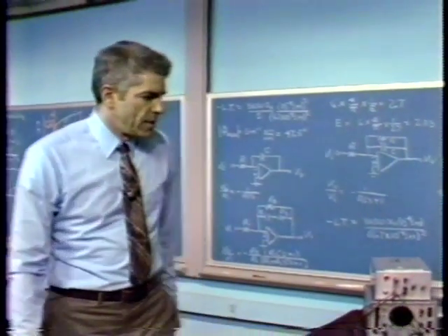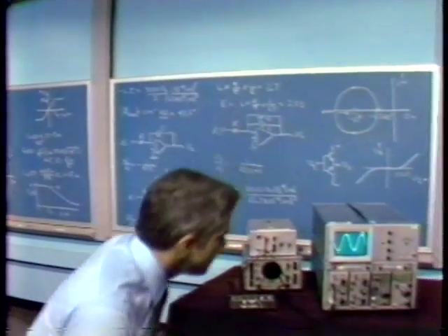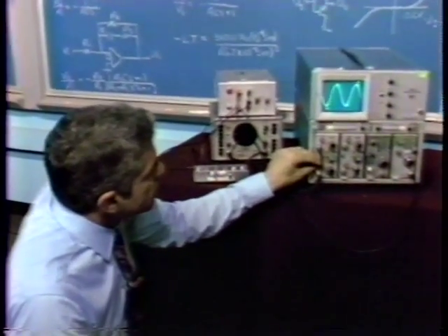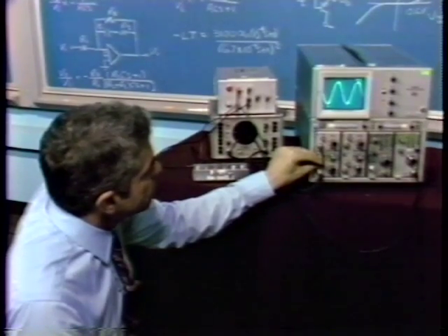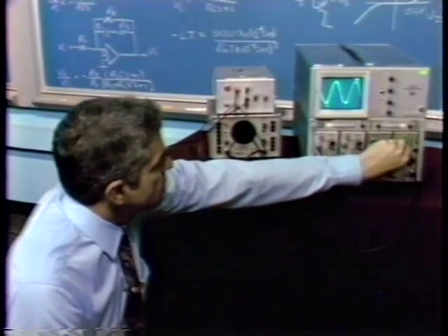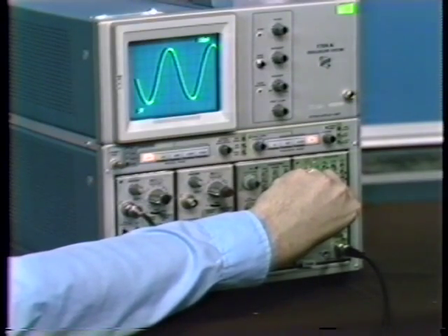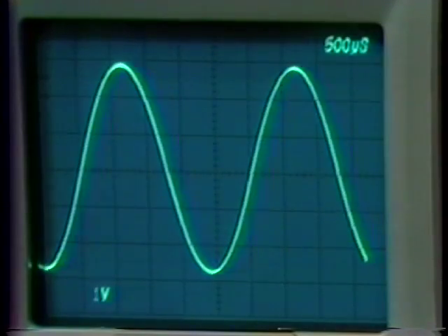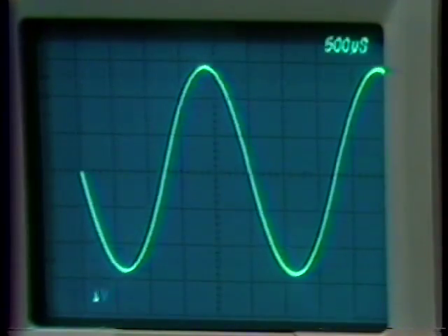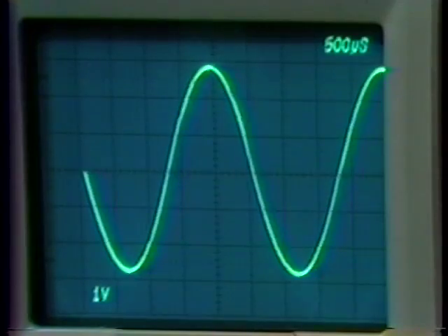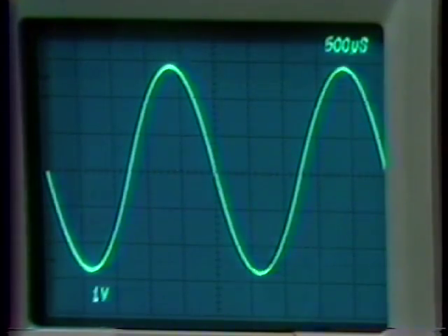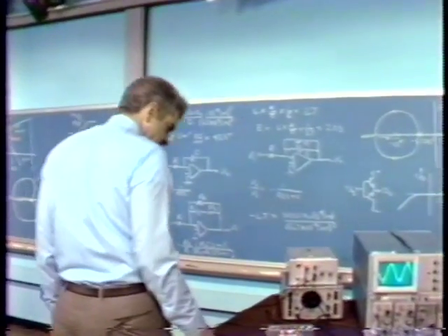Let's look at the sine wave. Again, we're at 1 volt per division. And it's certainly within experimental tolerance, we'd conclude that that's very nearly 2.83 volts peak. We have close to 3 volts peak, and if we look at the fine division, we just about cross the 2.8 volt minor division. So again, to within the accuracy of our experimental configuration, we conclude that describing function analysis predicts the amplitude of the oscillation very, very well.